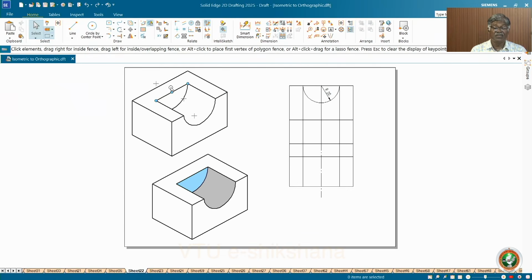Here is the line reference. Here I have to retain this line because this block, I blocked it here, and this is a flat surface represented by a line. Not that we are representing this edge, we are representing the entire surface. The surface here is not visible. U shape here. Now, in top view, this line is added, and these two are retained.